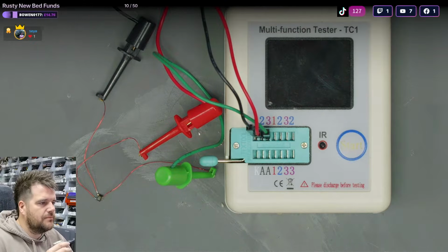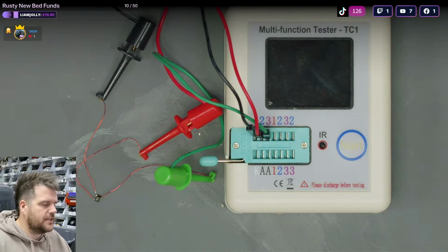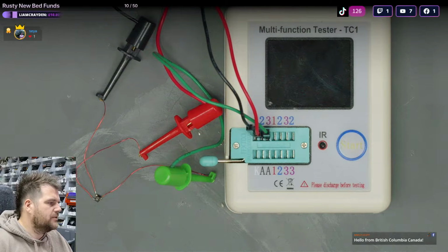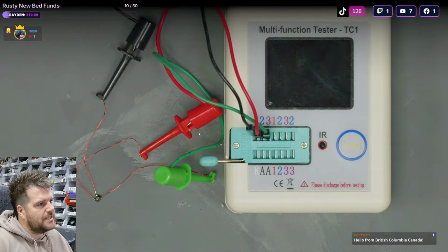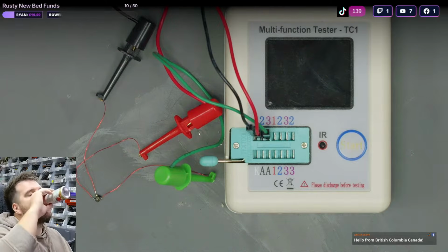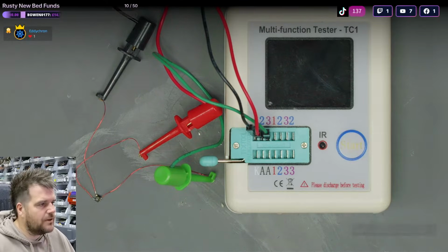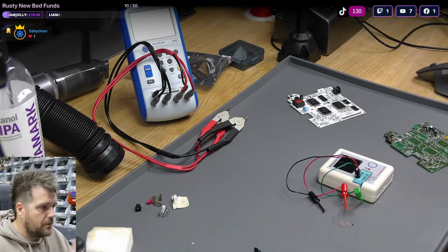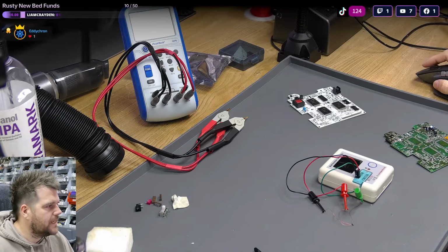I don't trust that test, basically. I don't think it's a diode. I think what it is is a dual diode, and this test is getting confused and thinks it's an NPN transistor, because that's commonly how it'll test for an NPN transistor. It is by testing if two ways are diodes, and then if you can put current through one way. So I think it can misrepresent, with it being a cheap tester as well, the actual component. So let me just do a little bit of digging a minute.